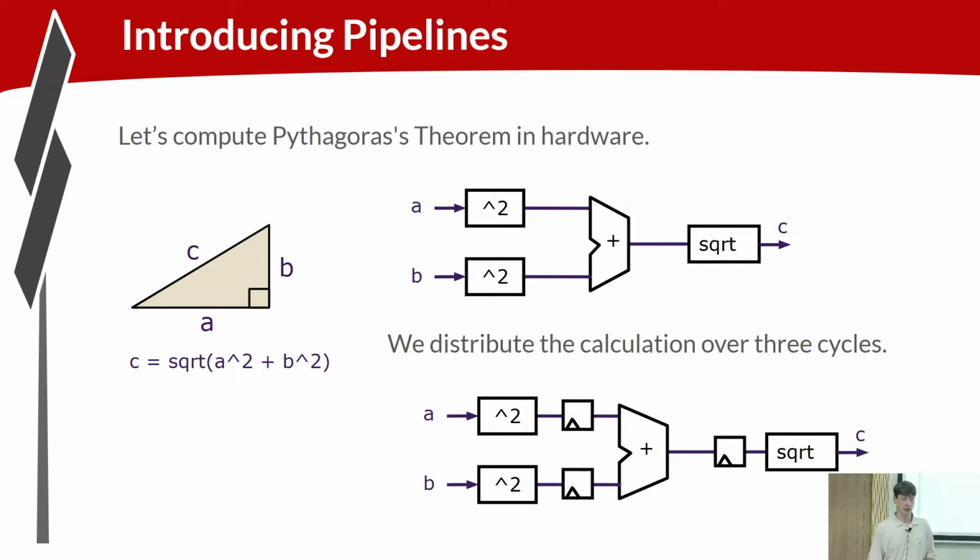So we have to partition the computation so that we're doing some logic in one clock, more logic the next clock, more logic the next clock. So simplistically, I've just divided these three steps into three pipeline stages by putting flip-flops between each computation. Square root itself is a very complex computation, and realistically we would not be able to do that in a single cycle, but this is just an example. Let's pretend. So we've got our three-stage pipeline to do these computation steps.